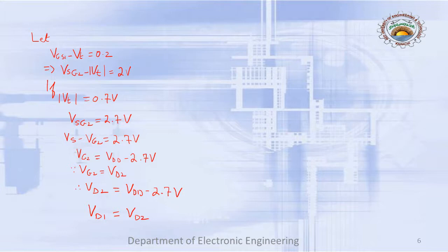Moreover, with the common source transistor and an NMOS based diode connected load, we would have a gain which would be GM1 over GM2, but at the same time there will be substrate effect. PMOS does not produce any substrate effect, but the voltage headroom is the price that we pay.